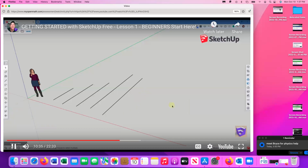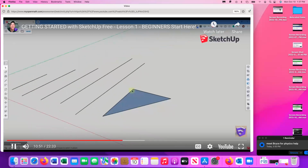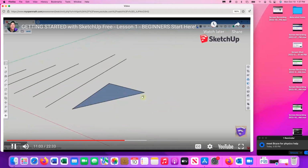Where SketchUp actually fills in the space between lines. So for example, if I was to draw a line this way, like this, and then like this, what you're going to notice is you get this filled in face inside of this triangle. Well, the reason for that is because SketchUp is what's known as a face modeler. And what that means is SketchUp draws faces anytime you have 3 or more coplanar edges inside of your model.